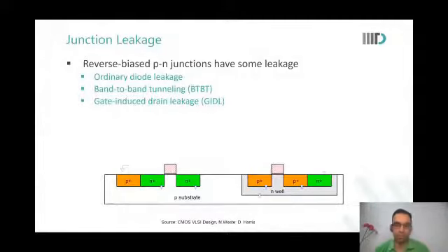Okay, sir. But Cadence would always give you the option to have that body terminal, and you may also want at some time to connect the body terminal. As a designer, you should have all the flexibility. For example, in a digital circuit, I would by default be observing this stack effect by virtue of my design only, because I have PMOS and NMOS in series. So sir, why should I select low VT devices? Because you want speed.